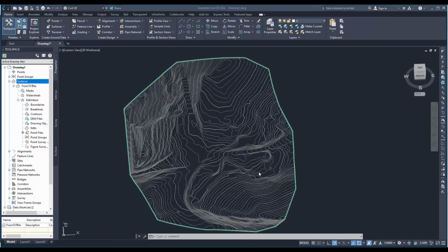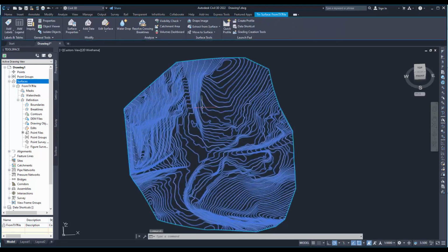What else? Okay, what else can we do with this surface? If we select it, we can, for example, calculate some vertical cross sections. We can also do that in 3Dsurvey. We can extract some objects from it. Whatever is visible here, we can extract. So here, extract objects.